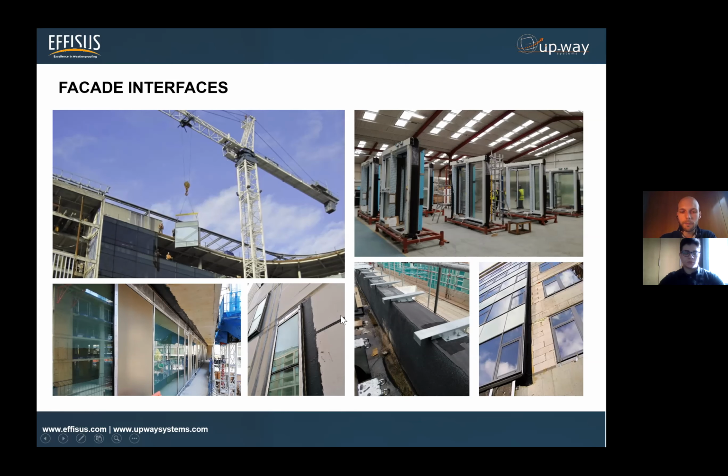So the sheeting board, you just need to do this kind of interface, or sometimes you need to deal with the coping, because you always have to do a connection of your facade to the roofing membrane. And so there's no way of doing this without an interface in order to get a complete waterproofing system in the full envelope of the building.